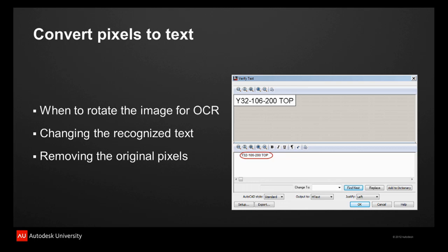process. Now how this works is in AutoCAD, when you select this text, it won't always necessarily be at orthogonal angles. It might be at a 33-degree angle or whatever the case might be. So you can't just go and draw a rectangle around the text. It needs to also know what the angle of the text is. So you've got 3 points that you have to select. The first point in AutoCAD, this is now on my text bar, but the first point would be at the bottom left of the text. Your second point would be at the bottom right, and that can be at any angle.